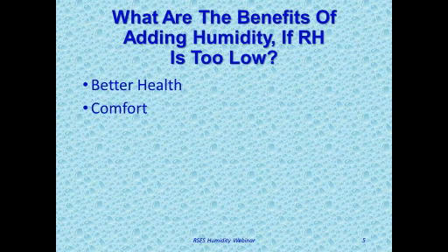Comfort. Comfort is a huge issue. If humidity levels are too low, we can be very uncomfortable and we require a little more heat. So our thermostats would have to be set higher. And we're talking predominantly about winter humidity.